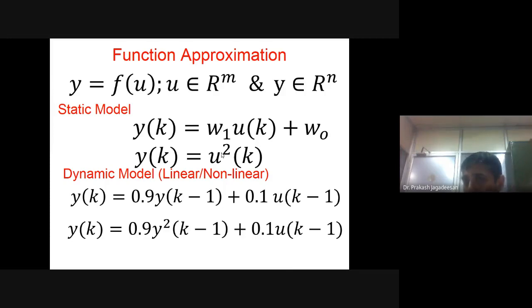For example, there could be bias in the sensor, maybe because the sensor is not properly calibrated. Maybe the output of the sensor would not indicate the true value. So sometimes we have to recalibrate the sensor, and in certain circumstances we have to detect outliers and remove outliers.